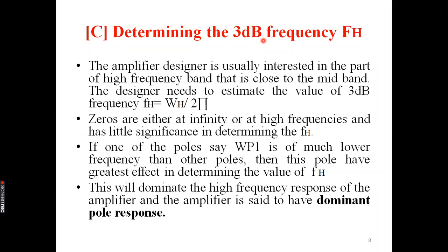But that gain, I'm not getting sustained for all frequencies. After a while, it is coming down. But that decrease is also fine for me. Till it is 50%, it is okay. Somehow I can manage my load working with that power. But what will happen if it goes below 50% of the maximum value? It is not that much desirable. So we call that particular frequency the half power frequency.